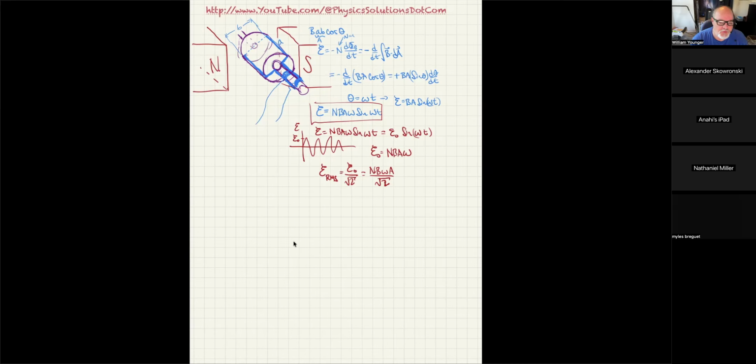So, a simple type of problem you might want to solve, just so you'll have an idea of what I think is fair game, is this one right here. This is example 29.10. It says an AC generator. The armature of a 60 hertz AC generator rotates in a 0.15 tesla magnetic field. If the area of the coil is 2 times 10 to the negative 2 square meters, how many loops must the coil contain if the peak output is to be E0 equals 170 volts?